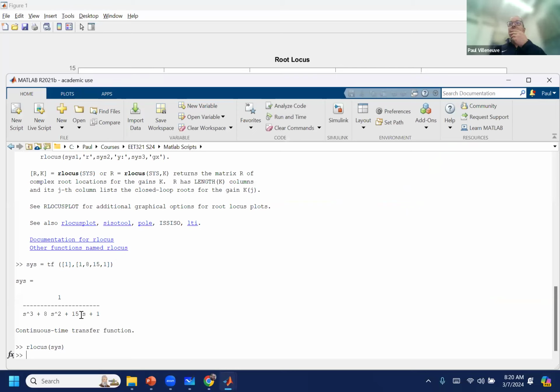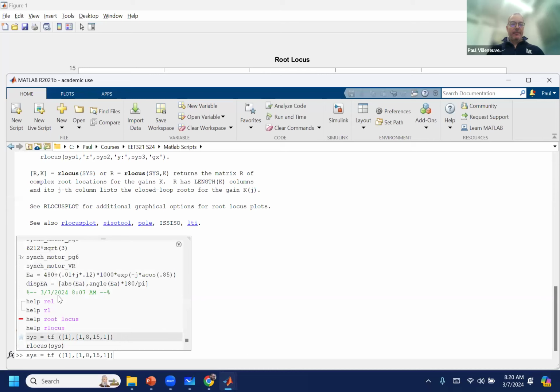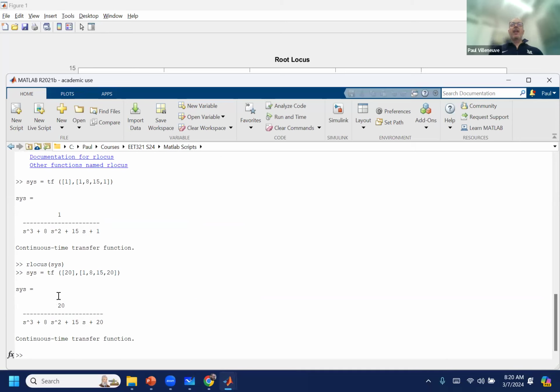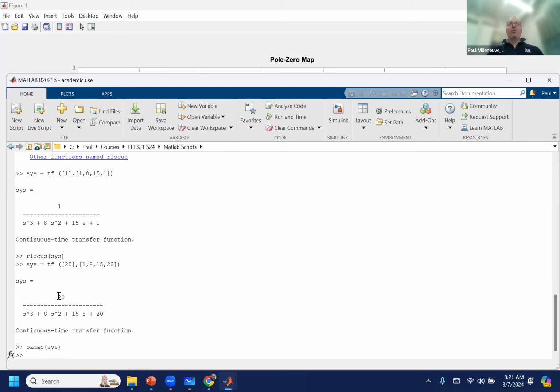If you change that value, if you put 20, how would you do it? 20 where? So we put one there for 20 and then one there for 20. So I put what, 20? Yeah. And then also the last one too, 20. How would you? You can't do a root locus because now the gain is fixed at 20. So at that point, I would do a PZ map. No, K is a variable, right? You can increase it.